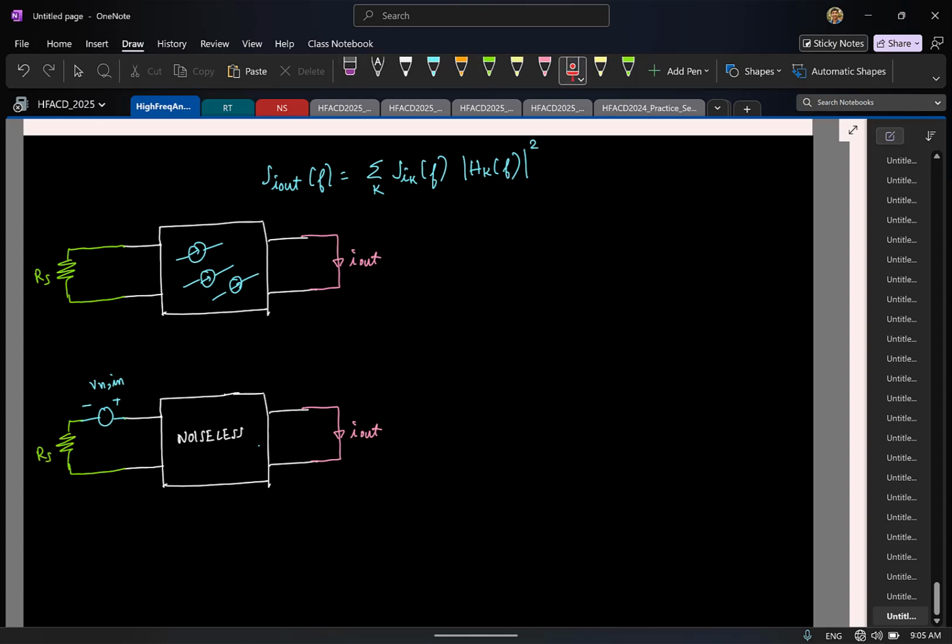Then we notice that only a fraction of this noise voltage will appear across the input, because now we have a resistive division between Rs and the input impedance. And in particular, if Rs is very, very large, and if Rs is infinity, this model predicts that the noise voltage does not appear at the input at all. But that's not what happens. You still have noise generated in the network. So to properly model the noise, in addition to the voltage, you also need to have the current.